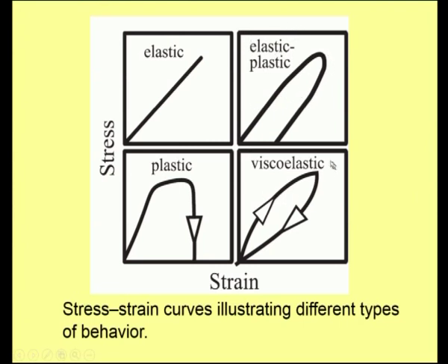This is because of the viscous effect exhibited by the material. Now you look into a visco-elastic material like a polymeric system. With the increase in stress there will be the increase in strain. Once you remove the stress, it will take a path, of course not the same path, but then it will take another path, but given sufficient time the strain will become zero. This is typical of visco-elastic material, which is similar to a hysteresis effect with respect to magnetism in metals.